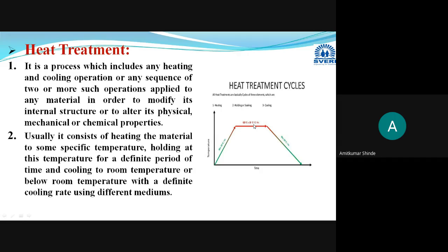In some exceptional heat treatment processes in steels there may be different phases, but here soaking is performed to get the homogeneous phase, and that phase is austenite. It is also termed the austenitizing process. Holding for getting the homogeneous austenite.